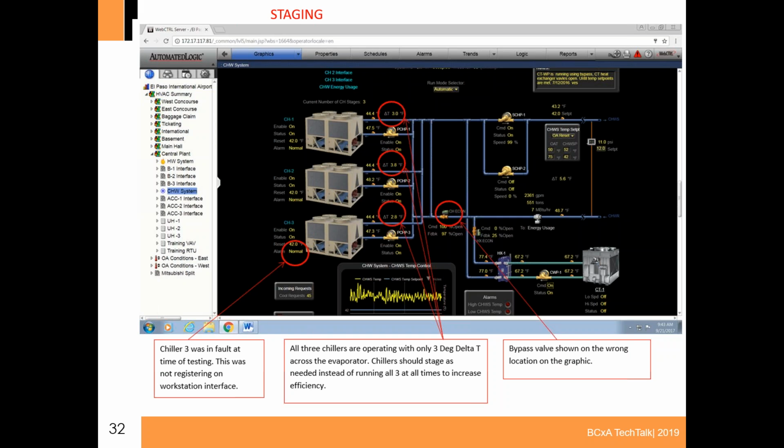Most things change relatively slowly in HVAC, like room temperature. Even if you start supplying 55-degree air or 90-degree air, it's going to take several minutes and potentially hours for that room temperature to change. Trending every minute or every 5 minutes, you're clogging up a lot of data and reducing the number of data points you get for a good graph. So for 90% of the things you care about, an hour is the ideal interval to balance the amount of data points, not clogging up the network, and still seeing what's going on.